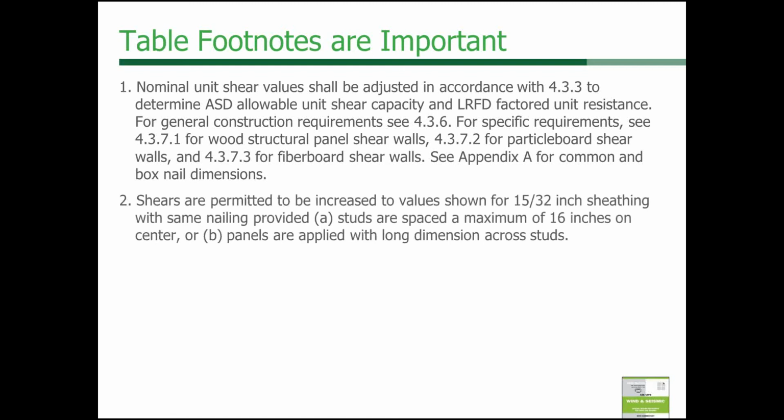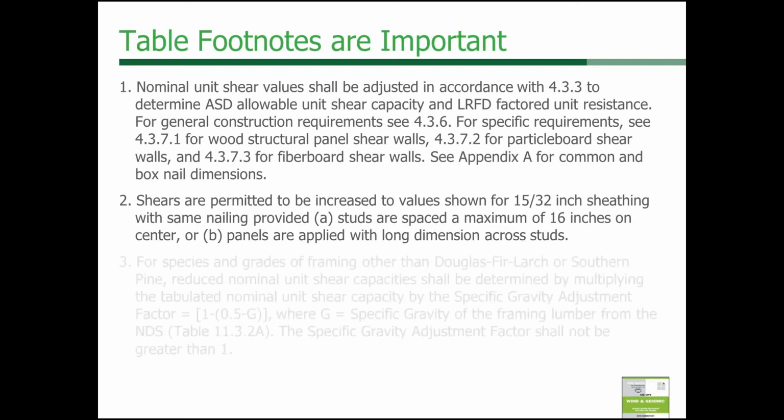Now, also, footnote 2, this deals with if your wood structural panel is 3/8 or 7/16, you can increase those values to the values of the 15/32, provided that your stud spacing is 16 inches on center, or if your panels are applied with the long direction across the studs rather than vertically. So an advantage, you can increase your values given these two different requirements.